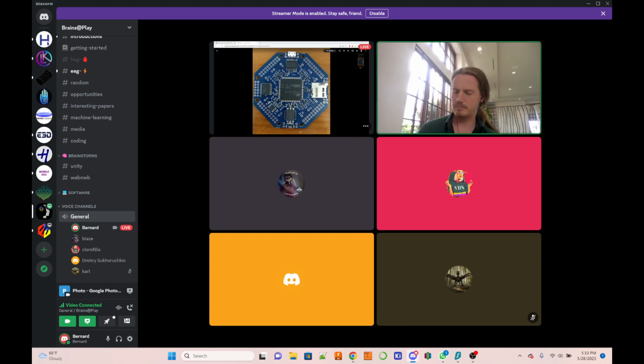Okay, I see. So out of the 11 double pin locations, we interconnect the 7 that do not have the 0 ohm resistors. Yes. Okay, so then what I said earlier about placing the header pins on all of them is not correct. It should only be on the 7 locations that do not have the 0 ohm resistors. Yes. Okay.